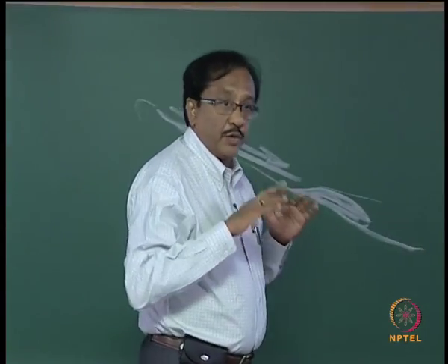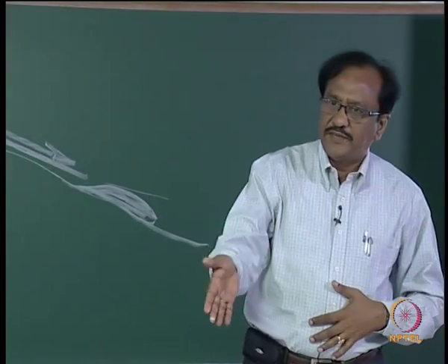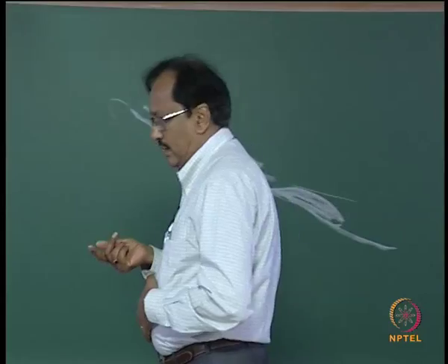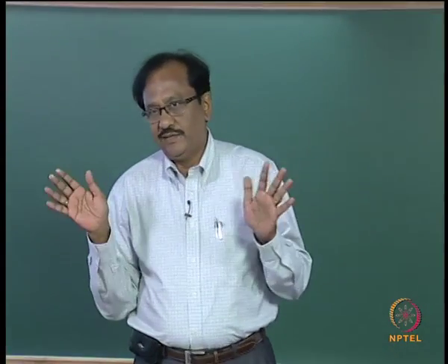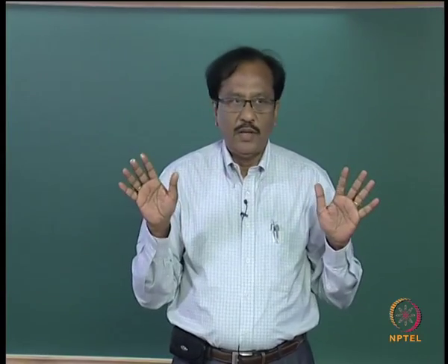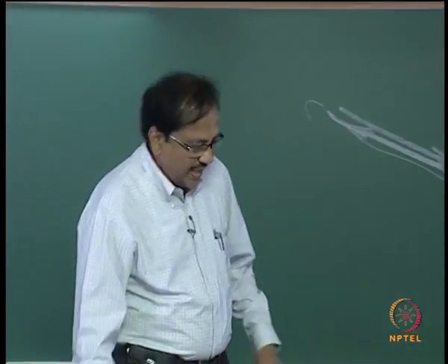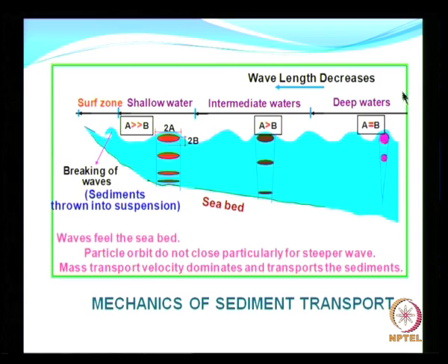But then we should also know how the sand which is lying in the seabed comes to the surface along the beach. That is very important. We have undergone the course on wave mechanics, and all of us know the physical behavior of ocean waves. What does that say? That says in deeper waters you have no effect of the surface waves on the seabed. So that means the sand in the seabed at this location will be more or less stable.